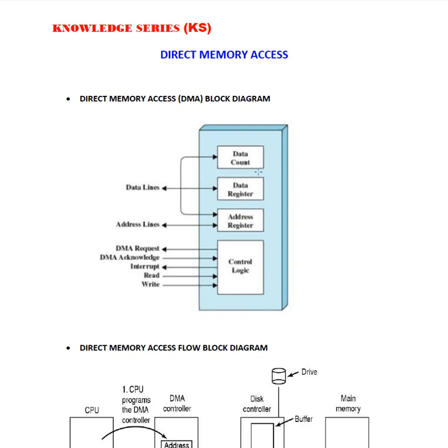Whenever data has to pass, the CPU has different registers, like general purpose registers, basically to store temporary data, and a segment register to hold the program with respect to the data or codes. The general purpose register stores the address lines as well as the offset values.